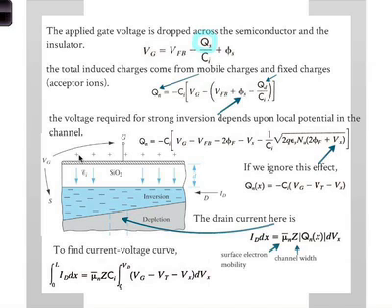Let's imagine that's just a metal gate. Okay, it's an oxide insulator. Then it's a P-type channel, so it's an N-type substrate. Okay, this is the N substrate. So we have a source, which is P plus. Then we have a drain, which is also P plus. That's my oxide. I want to know, how does the depletion layer look like here?